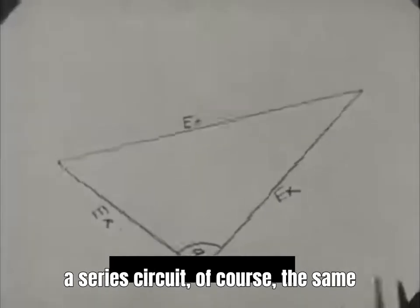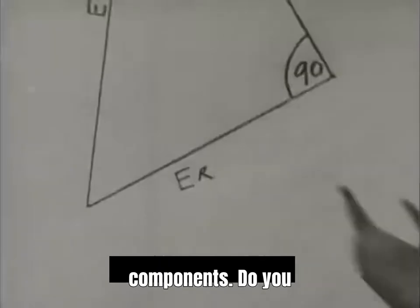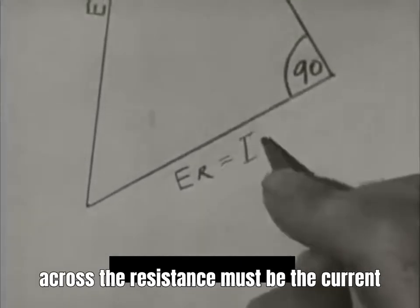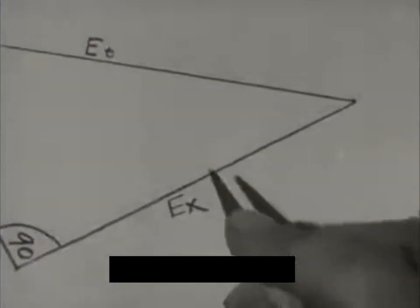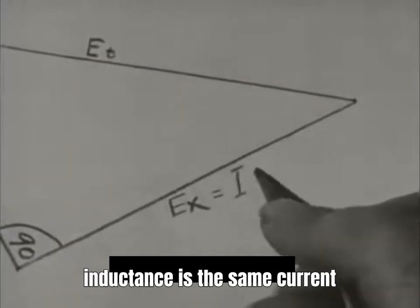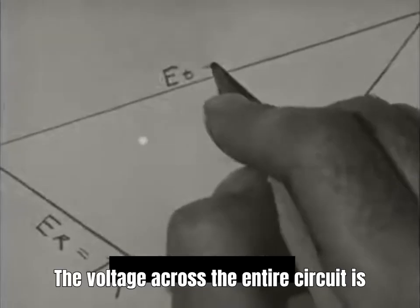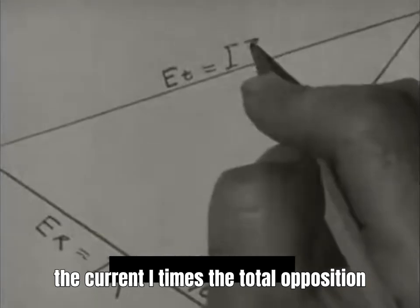In a series circuit, of course, the same current must pass through all the components. You know from Ohm's law that the voltage across the resistance must be the current I times the resistance R. Likewise, the voltage across the inductance is the same current I times the reactance X. The voltage across the entire circuit is the current I times the total opposition of the circuit.